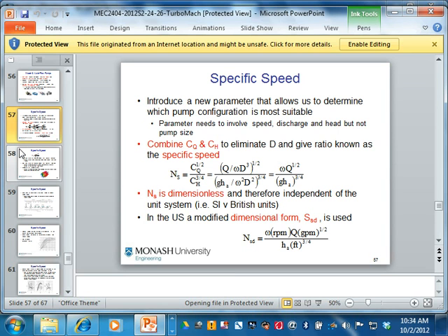High flow rate here. So high flow rate, this number big, you expect this number big. High head, this number big, you expect this number to be small. All right, that's the relationship. So a big NS is for high flow rate application, axial fan. Big H is for high head application. Small NS is for like compressor and all that, positive displacement.